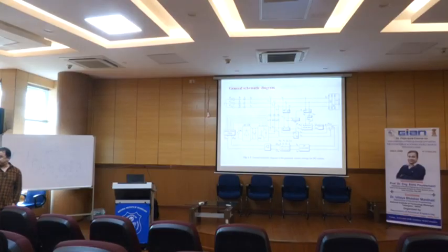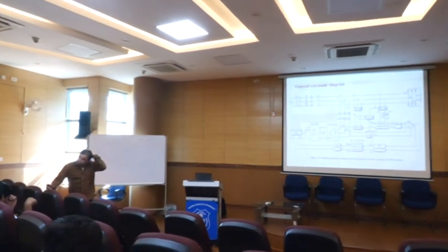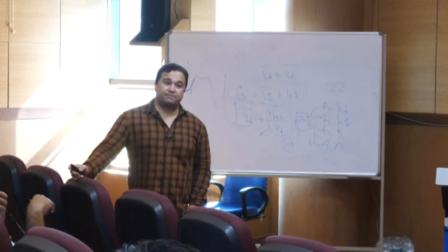Then it makes the delay. When it makes the delay, the PI controller follows the reference with the delay. So then it provides this fluctuation. Probably inertia is enough to damp a small fluctuation, but the main part is coming from the delay. Inertia and the controller also. Yeah, tuning of the controller.